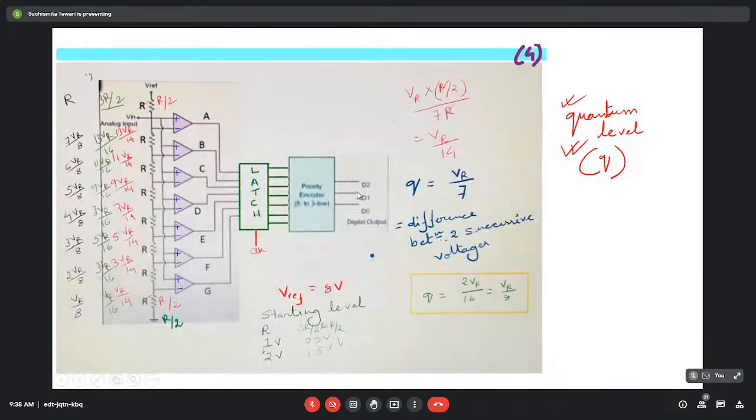So our aim would be to decrease the circuit complexity, or mainly we are going to focus on decreasing the number of comparators here, the number of these op-amps here. But the main advantage of this is that all the comparisons are done in parallel, and only one clock signal is needed to translate this whole thing to the output.